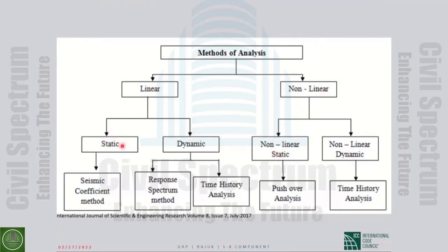Performing static or dynamic is mainly governed by the level of irregularity, not in the strength, but mainly on stiffness and mass.